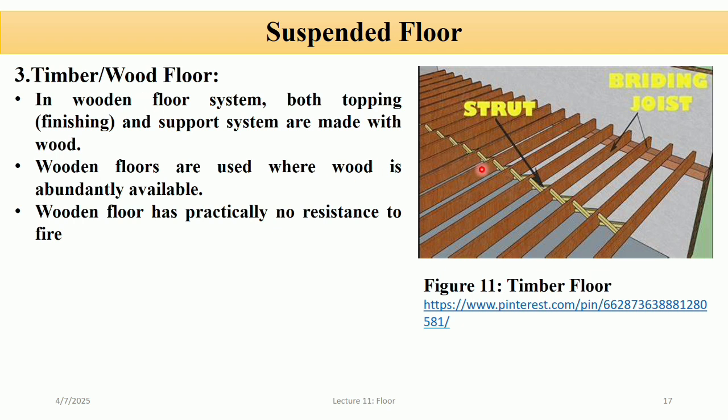We cannot use it in that. So it has very poor fire resistance because it would burn easily, making it unsafe in case of fire, and it is not suitable for heavy loads or large spans unless special treatment or reinforcement is added. And it can be affected by termites, moisture, and decay if not properly maintained.